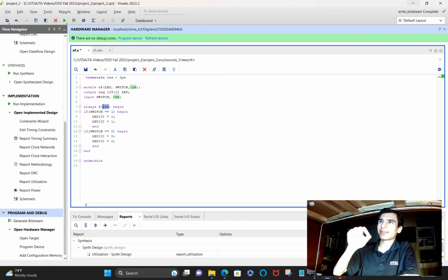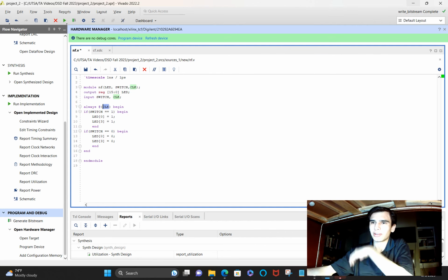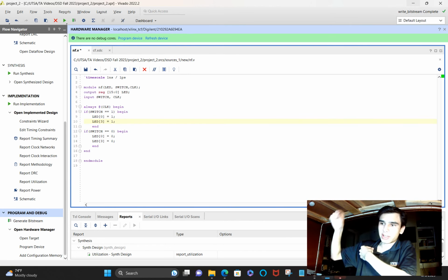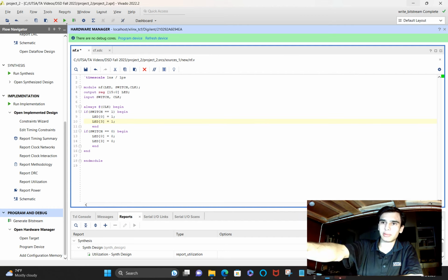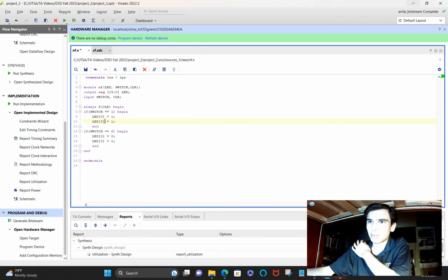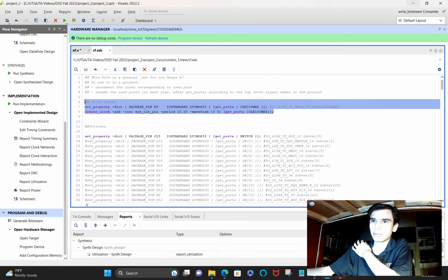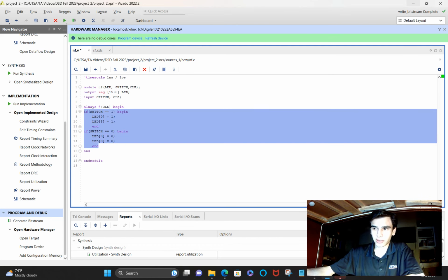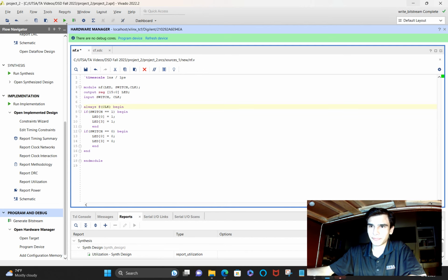What that means is on the rising edge of the clock, it's going to execute all the code that's in there. If you have a very, very fast clock, there's going to be a whole bunch of rising edges happening very quickly, so it's going to look like it's happening almost instantaneously. But if you were to slow this down with a whole separate clock divider module that we will discuss in future labs, and use that modified clock, then there would probably be some kind of delay, because it's all synchronized with that clock.